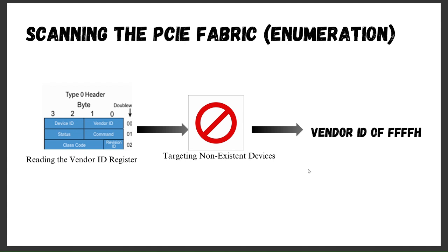Now, error handling during enumeration. Although a master abort error or a UR response could be seen as an error during normal runtime, it is expected during enumeration and not treated as a critical issue. The system uses a special unsupported request status bit to note these conditions without halting the enumeration process. This is important to prevent unnecessary error handling during this stage, as the system might not yet have all error handling capabilities active.